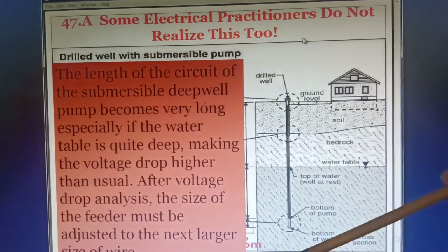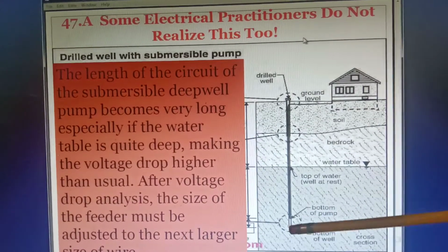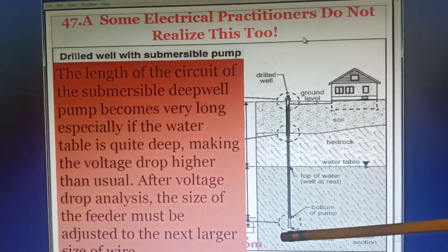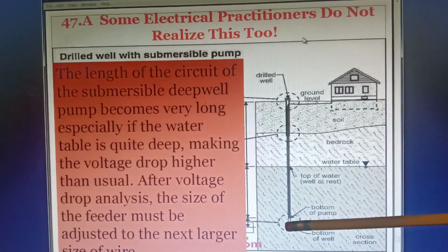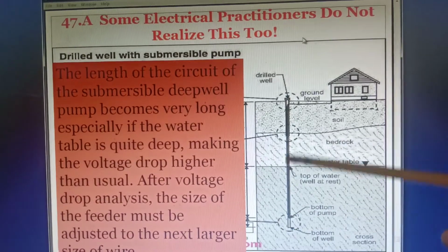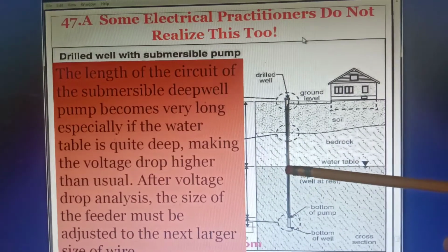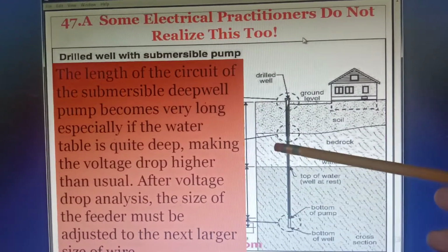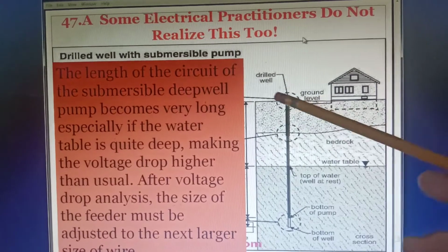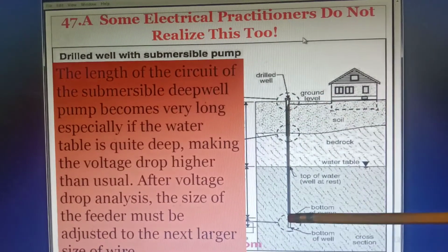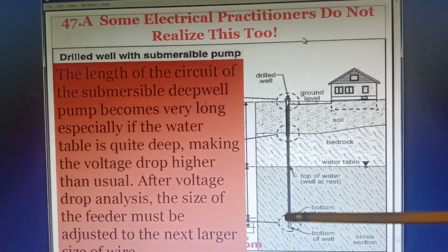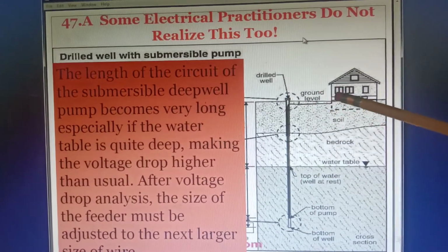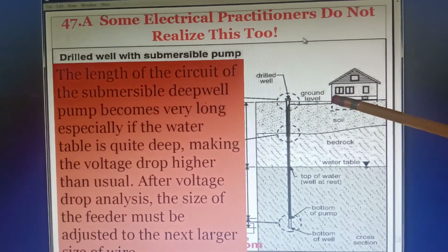So this is the reason why, very simple reason, that a deep well, which could be with a depth of say, for example, 20 lengths of 20-foot pipe, and that would be equivalent to about 400 feet below the ground, therefore that very deep well, depth of the deep well, will have a very long feeder up to your panel board or breaker.